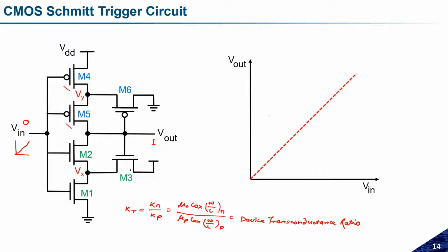But if you see here, what about the feedback transistors? If the output is equal to 1, this will activate transistor M3. And if this activates transistor M3, this logic will transfer here. So the Vx voltage here will be something different than what we expected. Here we have some voltages because it is the input. I'm assuming both these transistors are in the off state, but because the M3 transistor is in the on state, it will provide some voltage over here. That can change the effective resistance of the path, so this Kn by Kp ratio will change. How it will change, we will see mathematically.